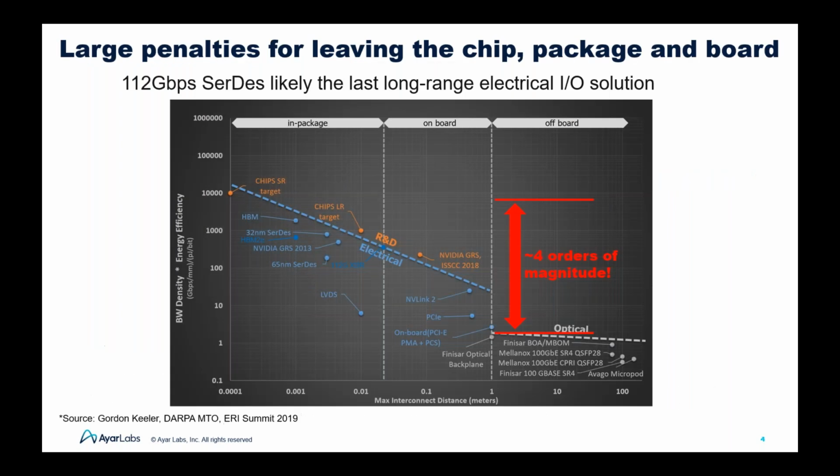Meanwhile, when we look at the power for optical I/O and the other electrical links available, we can categorize them in three levels: one is in package, one is onboard, and another one is offboard, which we refer to as optical modules these days. We see that electrical links, the SerDes, the long reach one, at least for now, have saturated at 112 gigabit per second. So far, we haven't seen any good proposal for 224 on the long reach. That's going to be a limit for electrical as well, and how we can solve this problem of the electrical.